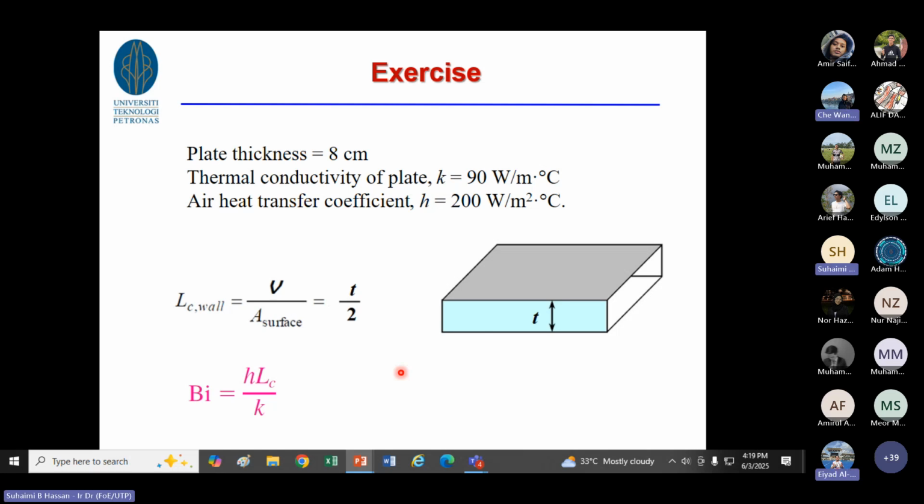Accurate. What's the value? 0.08. Okay, so 0.08 is less than 0.1, right? Then you have to put there: the Biot number obtained is 0.08, which is less than 0.1, so the lump system analysis is accurate. And you get marks from there. Is that clear for the Biot number? You have to write the statement. Okay. Second one.